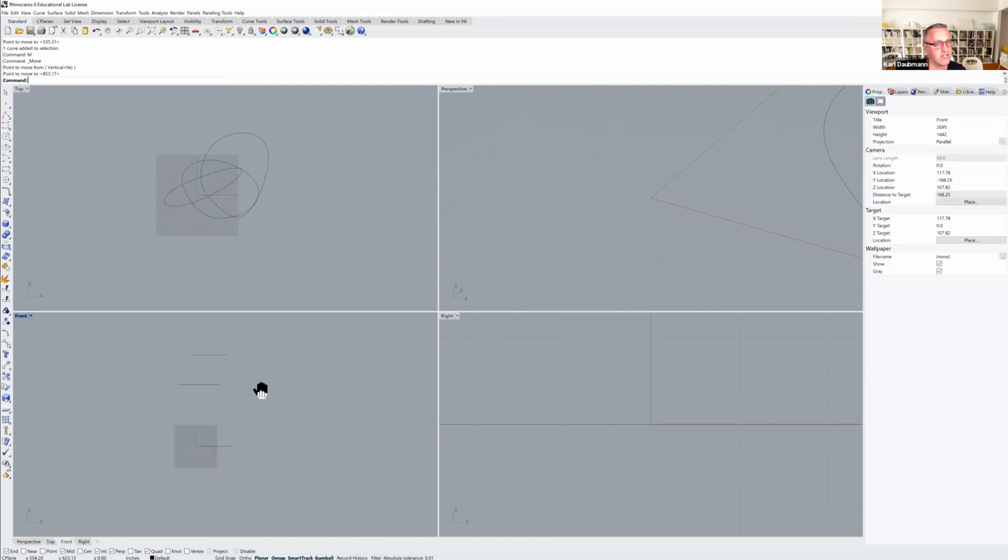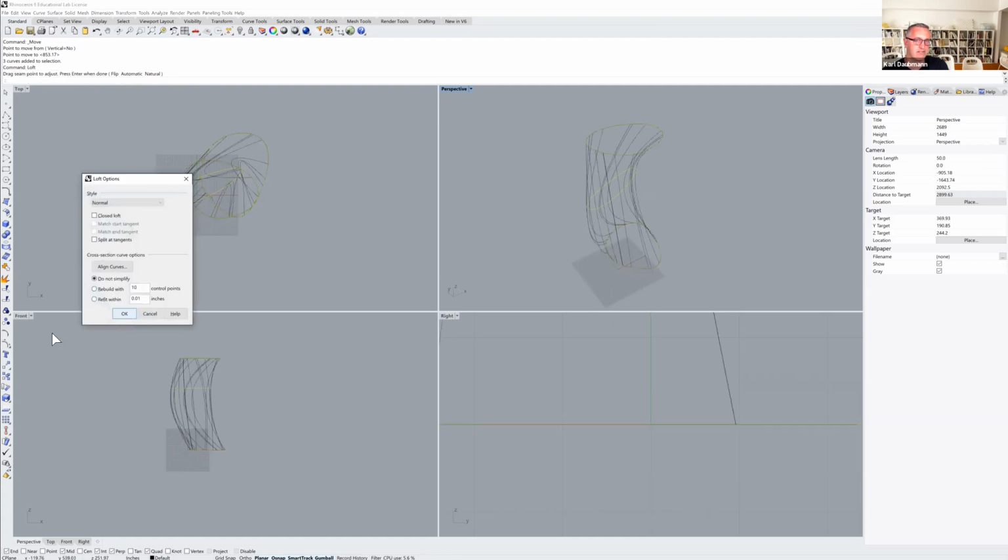And here's another, I'll show you guys how I work with iterations sometimes as well. Now we've got these 3 curves. We can select all 3 and we can loft. Now it's getting a little more specific. What it's showing you before it lofts them is the direction of the curves. We can play a little bit with this, but as long as your arrows are all moving in the same direction, it should basically work.